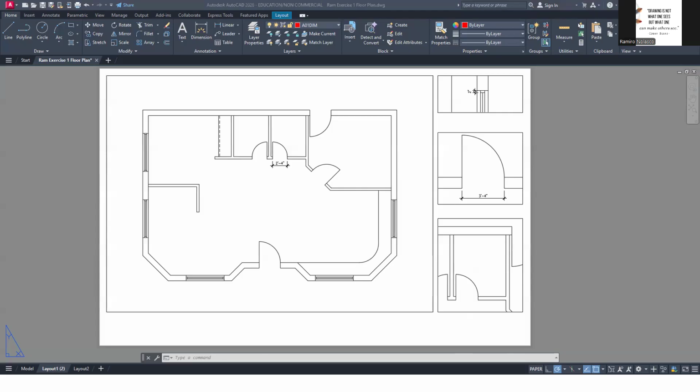Why is it so small? No, sorry. It's not showing the entire thing. Bigger. Here. That's one. Did you get what I did? I went here and added the text here, maximizing it so it's not too tight. Added the dimension, okay, and then minimize it, and you can see not showing. You have to put it in the proper viewport. So I suggest you place the text in the proper viewport.